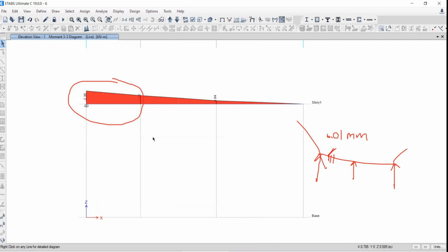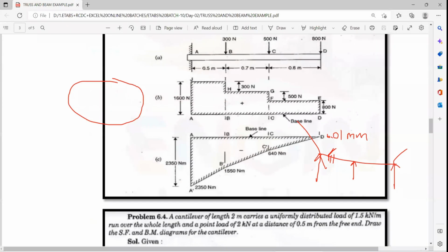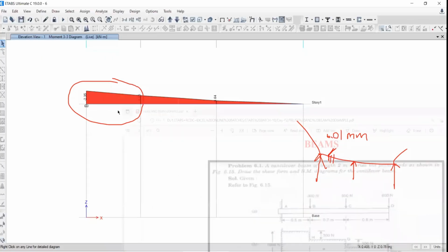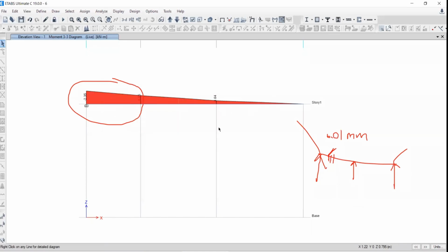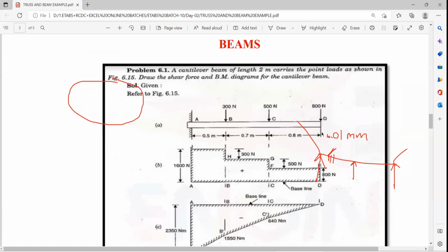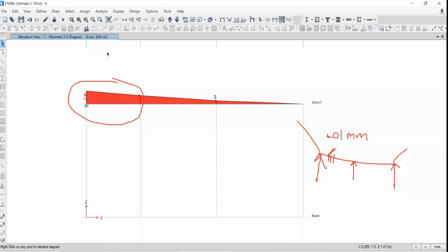But that is not the important thing. The important thing is, actually, this beam is a single element and we have modeled all of this in 3 parts. Okay, right, it is no problem, but I feel it is not more correct. There is an option. We can model it as a single element. But if we make a single element, what problem will come? We will not be able to give loading at a point. Assigning the loading will be difficult. Okay, so that is not the case. We can do it.